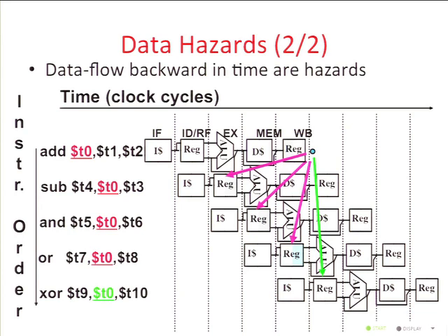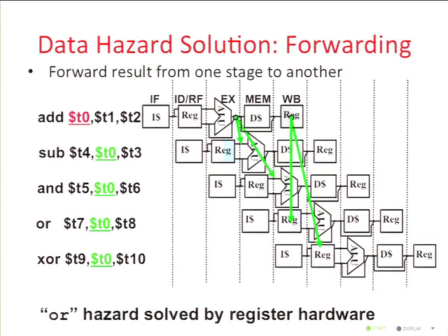What we're going to do is exactly what was said earlier, which is for these, we're going to read the results directly from the ALU. Okay? So we're going to forward there and there. That's going to be a little tricky. We're going to have to do that through a register. And then this one is tricky with the OR because that's actually in the same cycle.